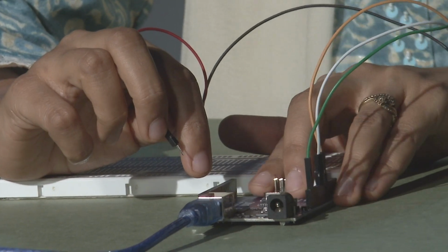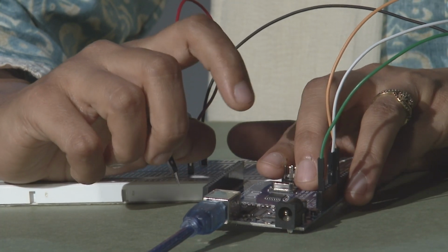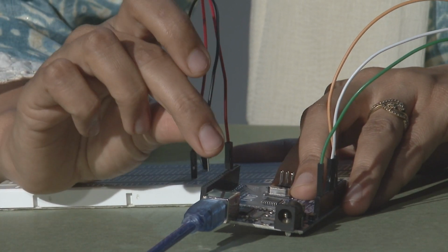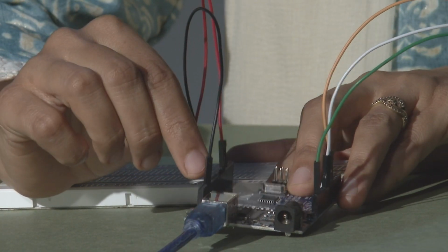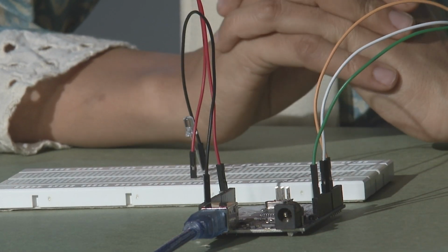So, this red one I will now be taking further to the signal pin, on which I will be creating my interface with the help of your LDR. Let us consider one of the pins from the digital port; I am using one from this downward portion, and the other terminal I will be using on the ground terminal over here. So, these are your basic connections ready on your hardware side.